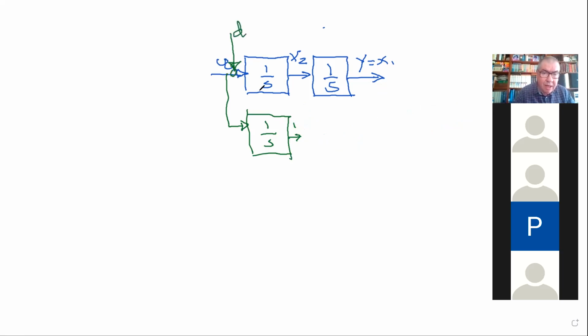You would have a problem because your x2 does not know anything about the disturbance. So this D would change a lot x2, but you are still estimating as if there is no D, because this is a kind of open loop system.